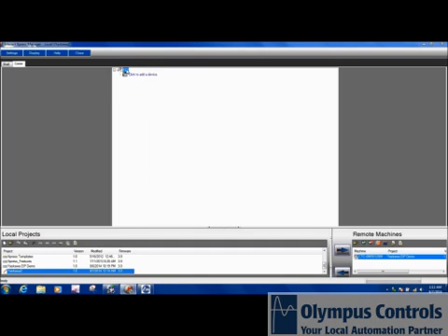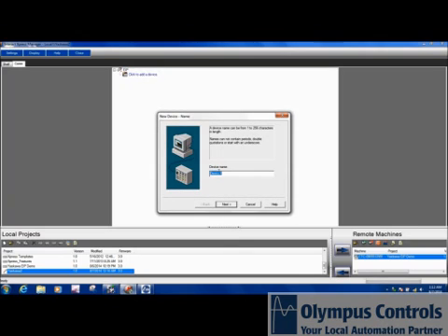Underneath that Ethernet IP network, we're going to add a device. Sorry, this is one PLC, but we could add multiple PLCs to the network. I'm just going to call this CLogix, and it's not a ControlLogix. Our demo is a CompactLogix 5300. Click Next. And the device ID can be a little bit tricky.